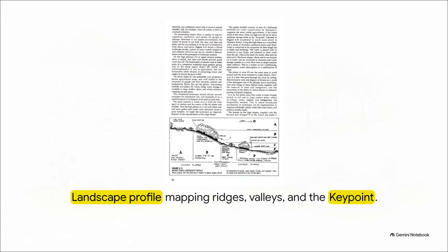As you can see illustrated here, a landscape naturally separates into dry, convex ridges and wet, concave valleys. Gravity naturally wants to pull water rapidly down off those high ridges and concentrate it forcefully into the valleys. The whole genius of keyline design is to purposefully intercept that water high up near the key point, and then gently comb it outward, pushing it back toward the dry ridges.